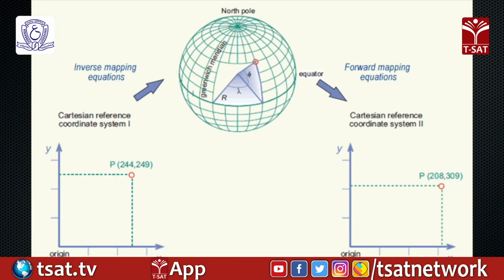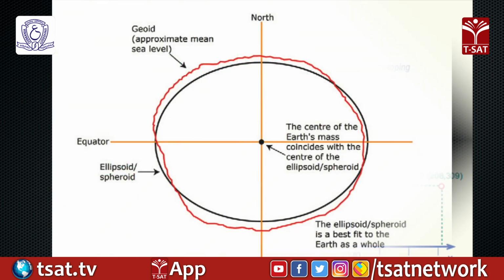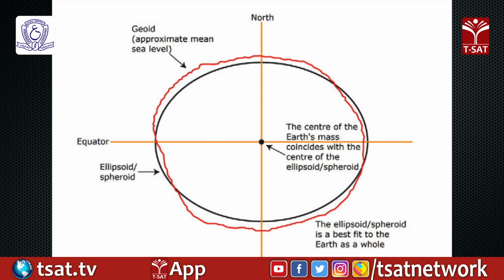To maintain the level of accuracy designed for measurement, a projected coordinate system is often divided into different zones, with each zone defined by a different projection center. Moreover, a projected coordinate system is defined not only by parameters of the map projection it is based on, but also the parameters of the geographic coordinate system, for example datum, that the map projection is derived from.